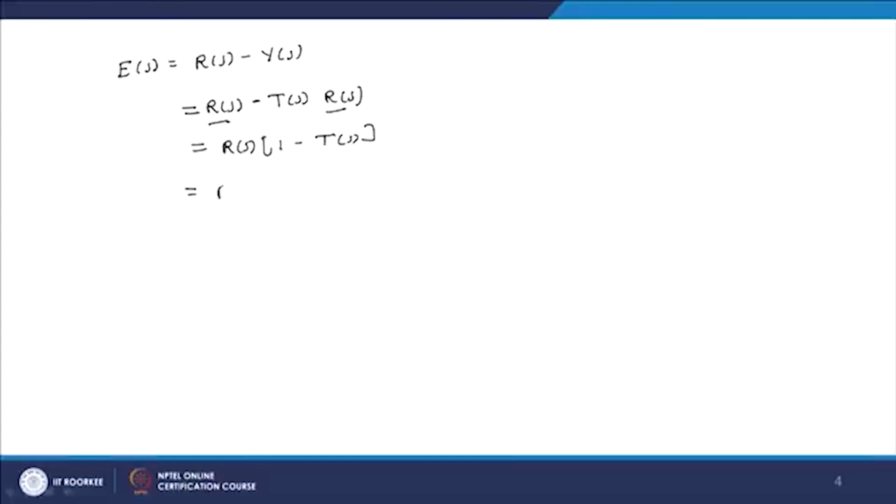In earlier classes, we have seen the conversion of a given transfer function into state space, and state space into transfer function. But now, here our input is not a numerator and denominator. Here our input is A, B, C and D. Here T(s) is written in terms of G(s), which is a part of the classical approach. Therefore, we replace this T(s) in terms of the A, B, C, D matrices. So, how do we replace it? T(s) can be written as C (sI minus A) inverse B, assuming that D is 0.